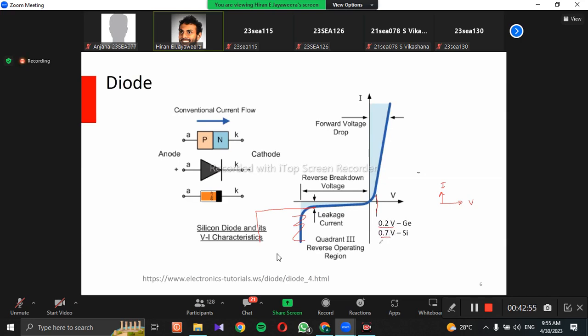And you can make different semiconducting materials like indium gallium arsenide. So we can have materials with different barrier potentials. Light emitting diodes are such devices. If you have a diode and nothing is mentioned about it, you can always assume it is a silicon diode, so the barrier potential is 0.7. If it is an ideal diode, it is mentioned. If it is a germanium diode, it is mentioned. Otherwise, for a typical diode, assume silicon with a barrier potential of 0.7.